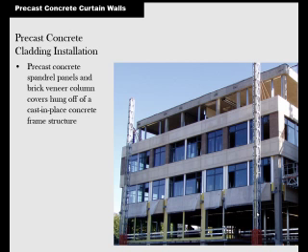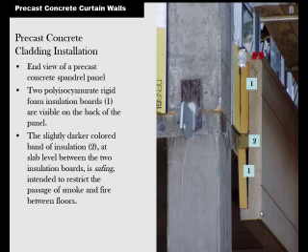Here's a building where they're doing the installation of some precast concrete cladding panels. You can see how it works pretty efficiently. Here's a good side view. You can see the insulation right there. You can see the fire stopping, or I think that's what that is, the slightly darker colored band of insulation at the slab level. Yeah, that's safing or fire stopping.